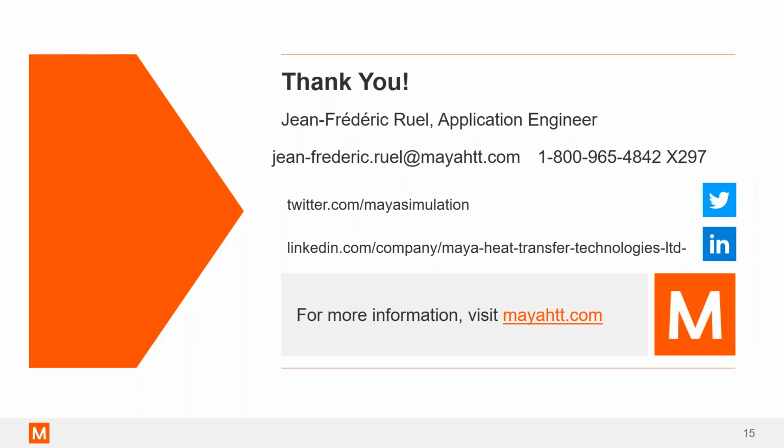Great, thanks, Jean-Frederic. Another question here, it just came in. It says, does Space Systems Thermal support ray tracing for view factor calculations? Yes, we do. So we have a Monte Carlo ray tracing method, as well as a deterministic ray tracing method.